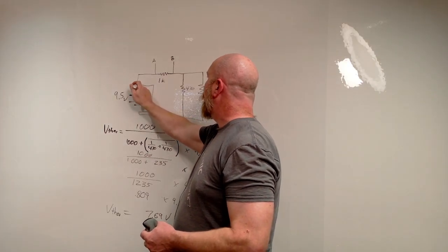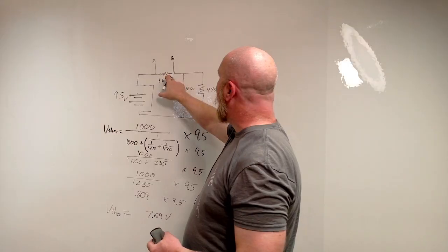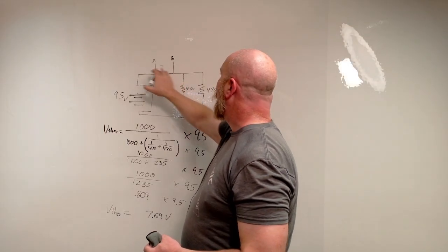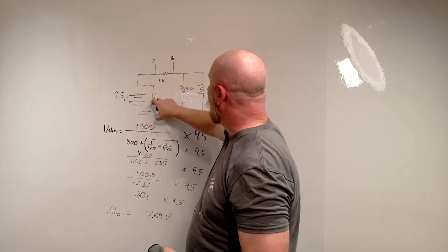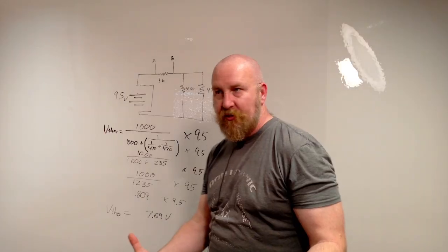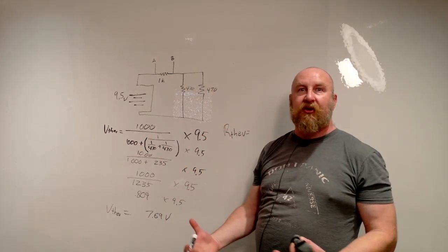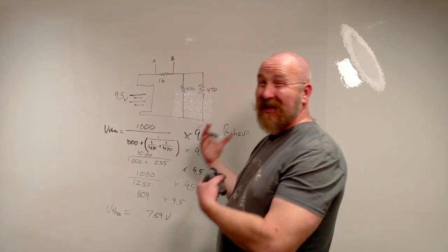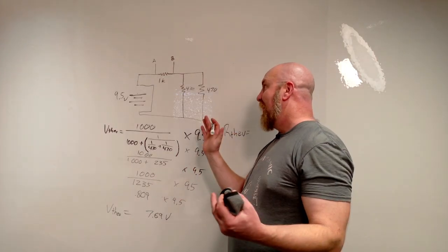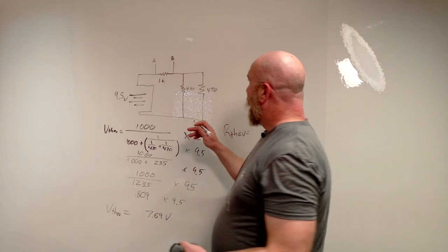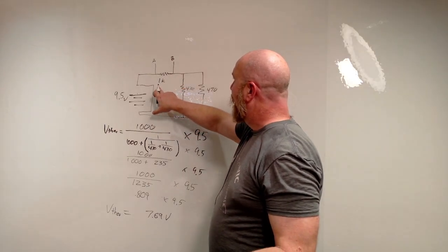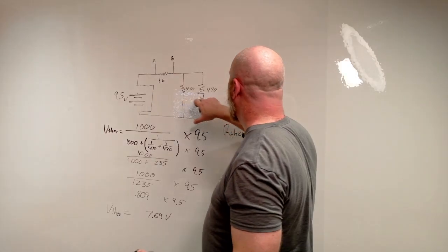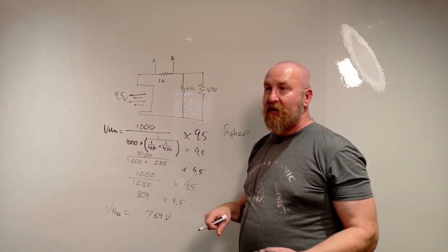And when we do that, we see that this can really exist anywhere along that line. In fact, we could move that resistor right here like this, so it becomes visually apparent to us, because we have to keep in mind the spatial logic of these things. What matters is the connections, not whether they're lying horizontally or vertically. We see that the 1K is, for Thevenin, in parallel with the two 470s.